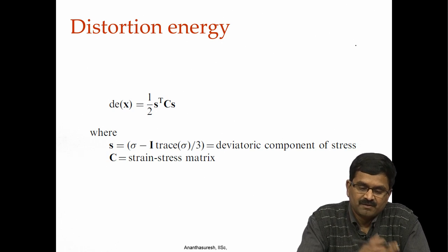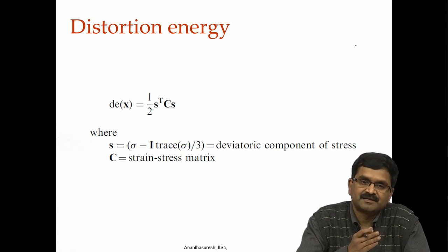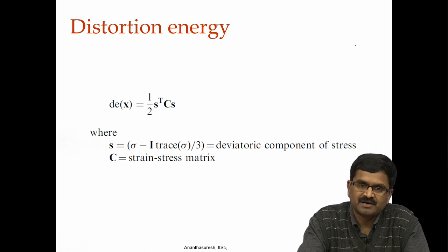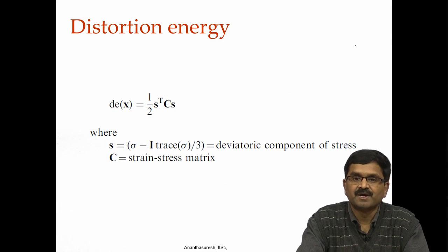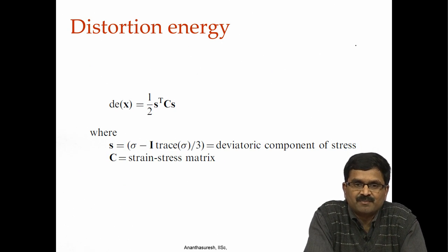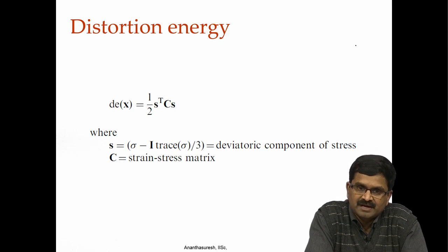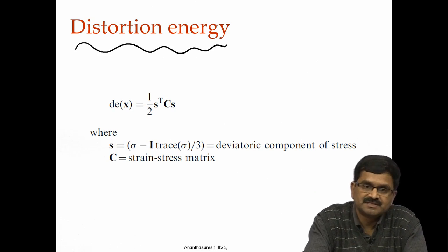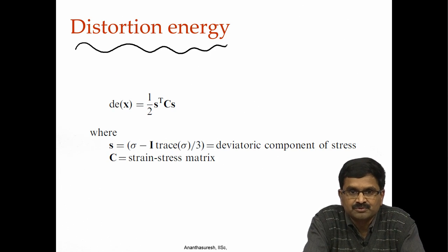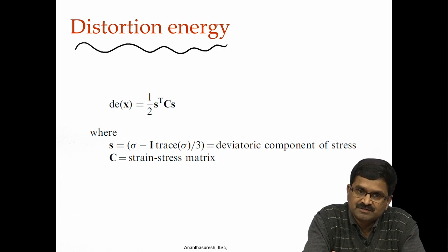Here is an idea. We defined this mutual strain energy, rather it was defined in early works starting from Barnett and Shield and Prager, and then later we used them to develop compliance and stiffness formulations for compliant mechanisms. Similarly, now you have to think about distributed compliant mechanisms. Let us think of an energy, and the energy we know from failure analysis that we all learned, something called distortion energy, meaning this is the energy that distorts the material mostly due to shear, and that is what causes the failure in materials, in ductile materials.